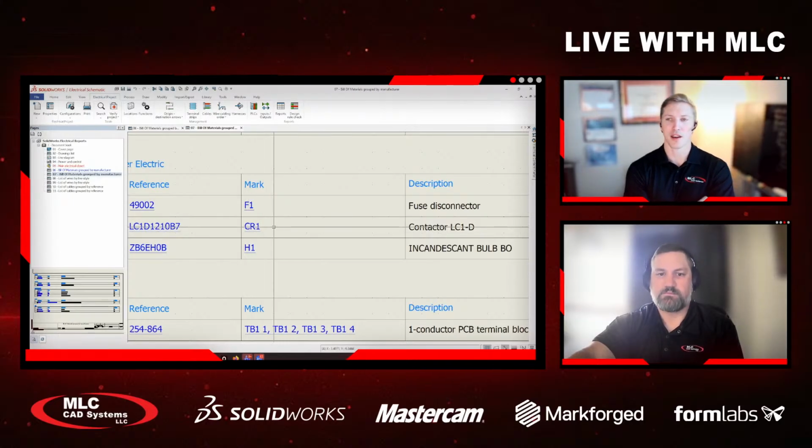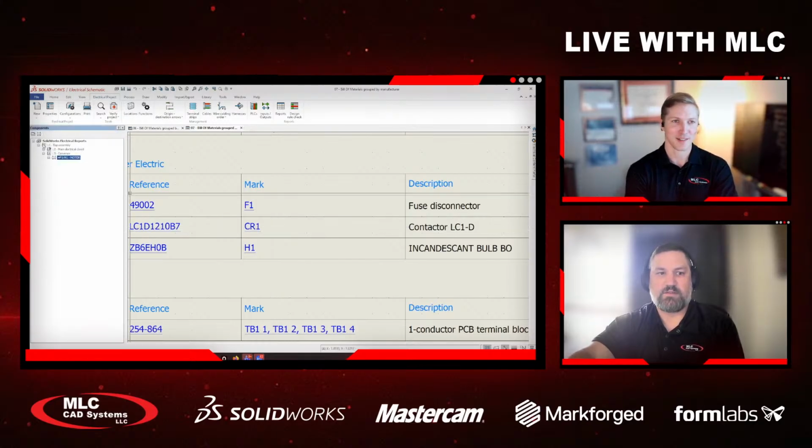Oh, yeah, okay, I can connect that now. Because I've seen symbols like you have your single line diagram, you probably have a simple symbol. Then you get deeper in power control. Okay, I'm with you. Yeah, and you can see that over here in the component list too. So if I were to go to one of these components like CR1, you're going to see that there's three what we call multi-line schematic symbols and then a line diagram symbol. So there's really four symbols and a 3D model that represent this device.